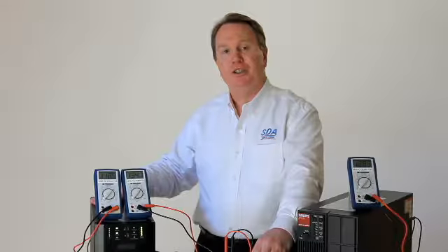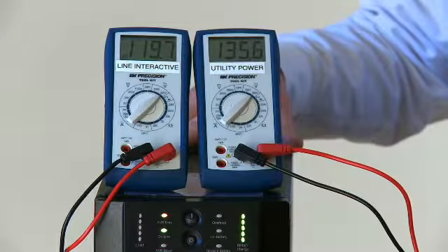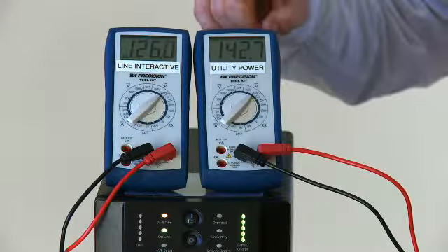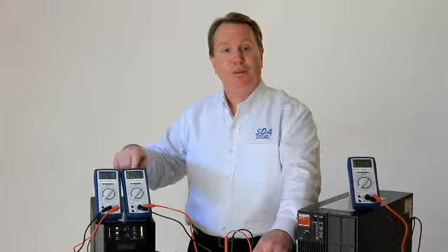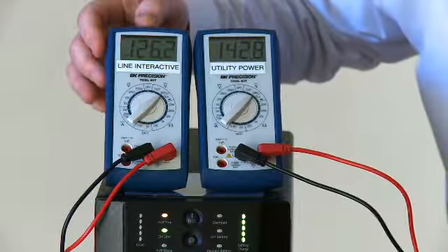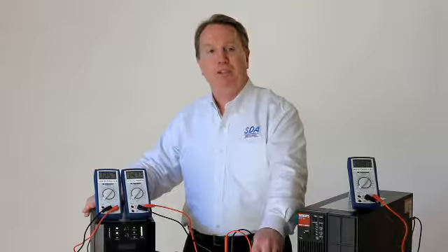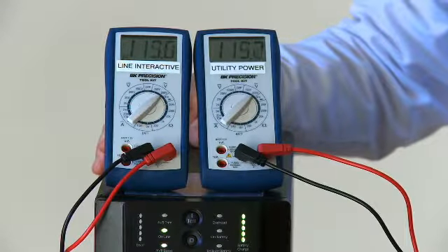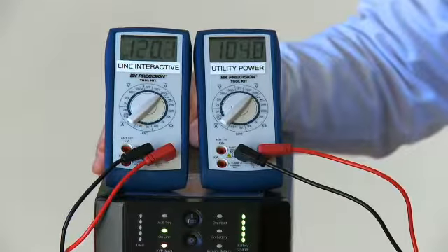What just kicked in is an automatic voltage regulator. It's the best this unit can do to protect the power quality level of the output. And now we're at 142 volts. Our output is at 126 volts. But what has taken place is we've had an electrical event called the AVR. Let's drop back. Let's spike up again.